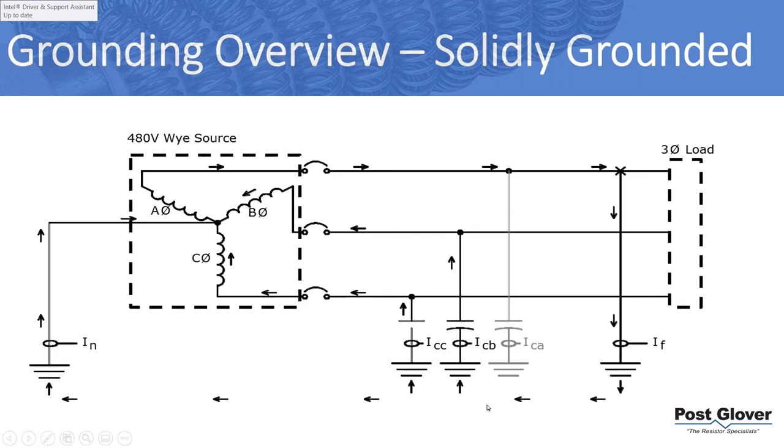So think about the same scenario I told you before. We have an intermittent fault or restriking, or that fault just keeps going on and off. We're charging that system. At this point, that's true. We are charging right here. However, over here we have essentially a discharge path. So this is a much more low impedance path. We're discharging much faster than we are charging. Therefore, overvoltage goes away in this scenario. So a solid ground system solves the overvoltage situation.